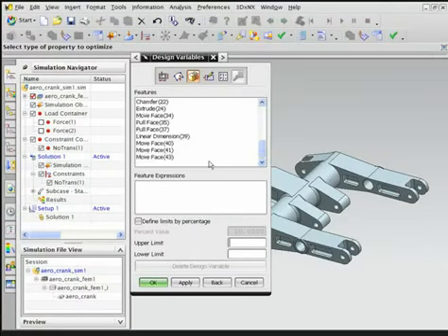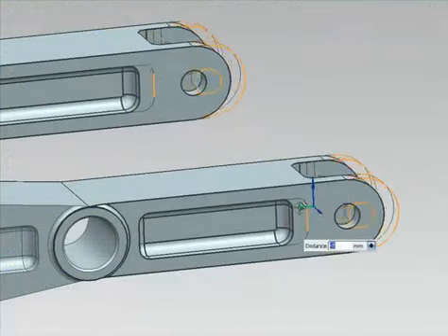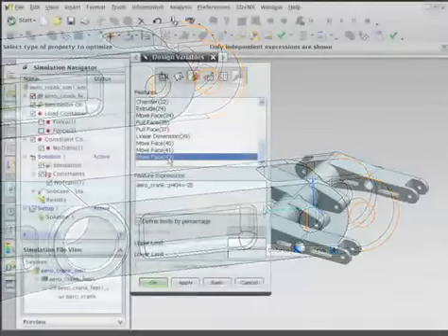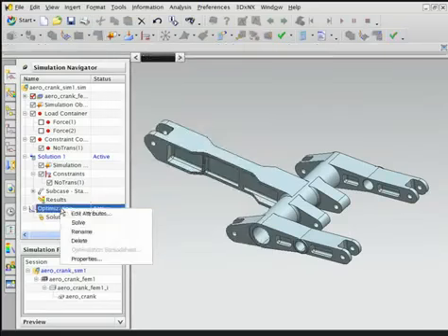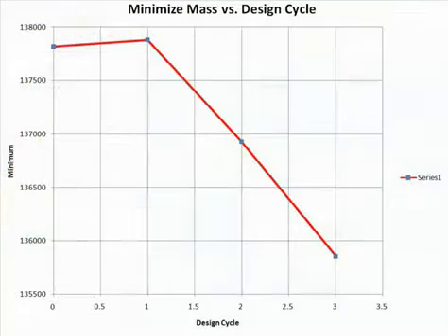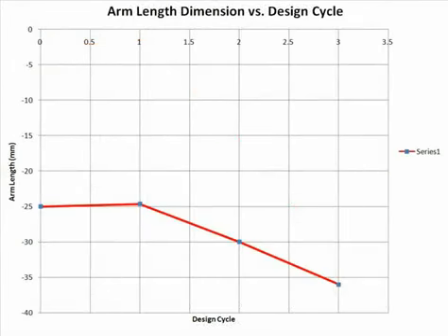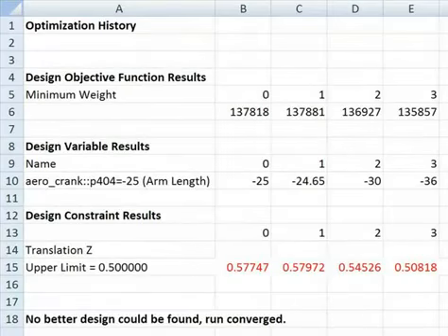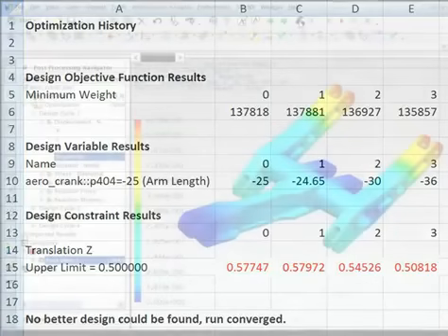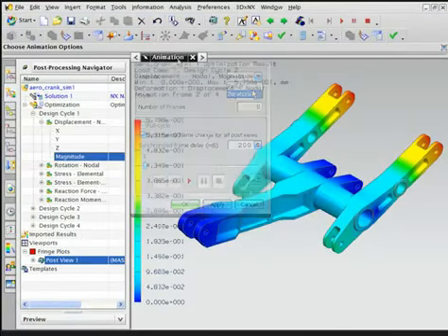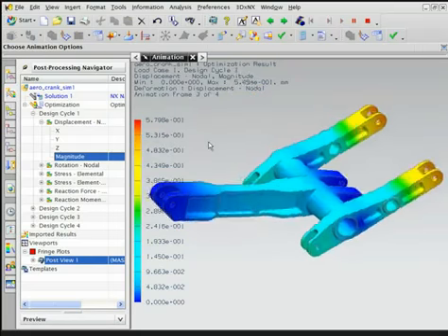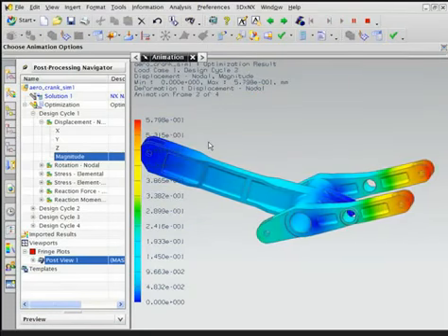You can then define a standard optimization solution and assign the geometry modified with synchronous technology as a design variable. Next, set the appropriate optimization limits and execute the optimization. Simple feedback allows you to see how the design variable changes in the objective function, followed by a report where you can see more details on how the design variable affects performance and weight. Finally, you can animate the results to get a clear understanding of what is happening with your optimization results.